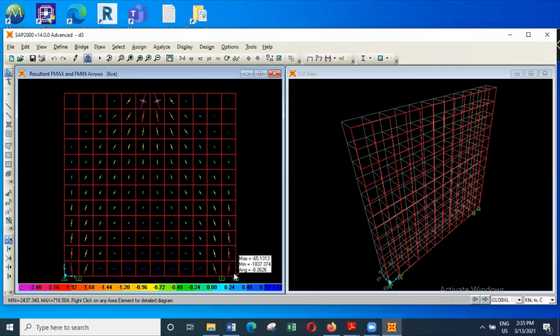Because of that, due to the flexibility of the wall, the wall will utilize the compression carrying capacity of concrete and shed the loads onto the 2 supports. But because these are at an angle, there is a compression. So this is the compression path.